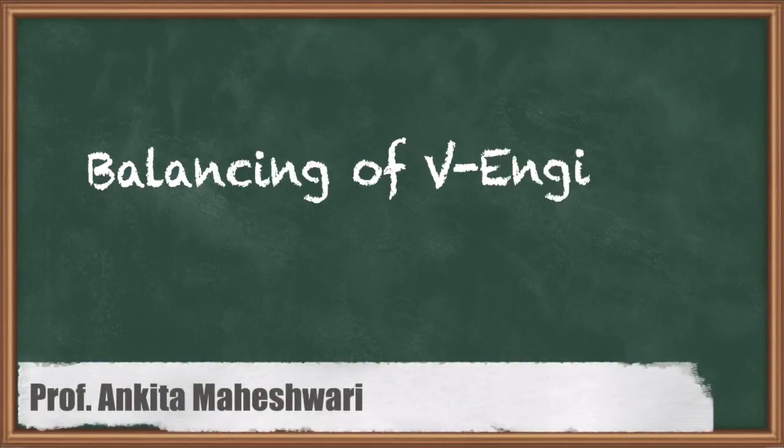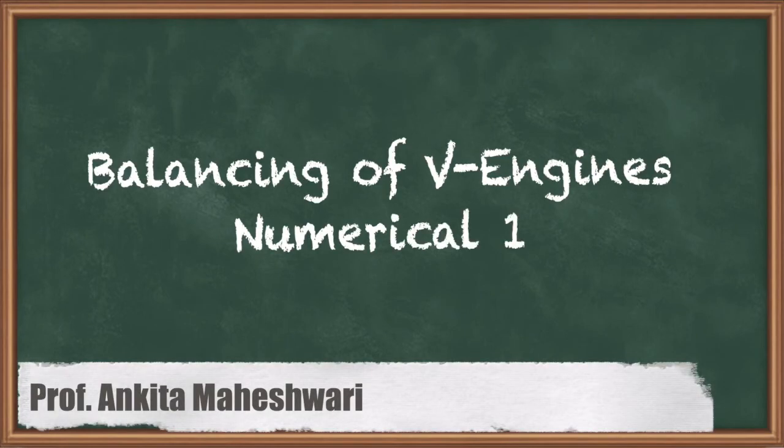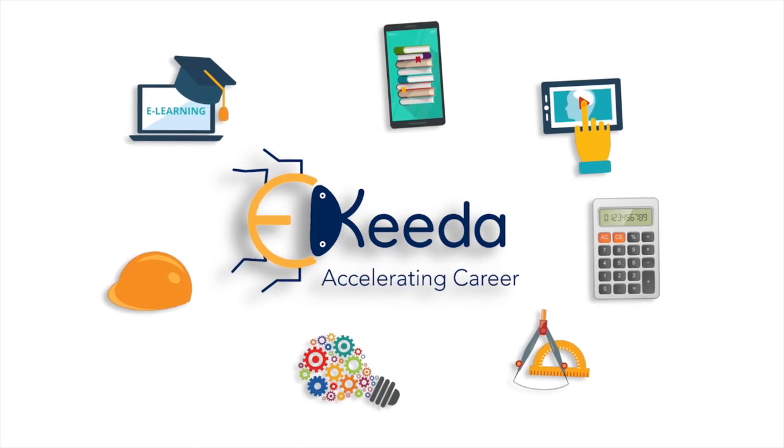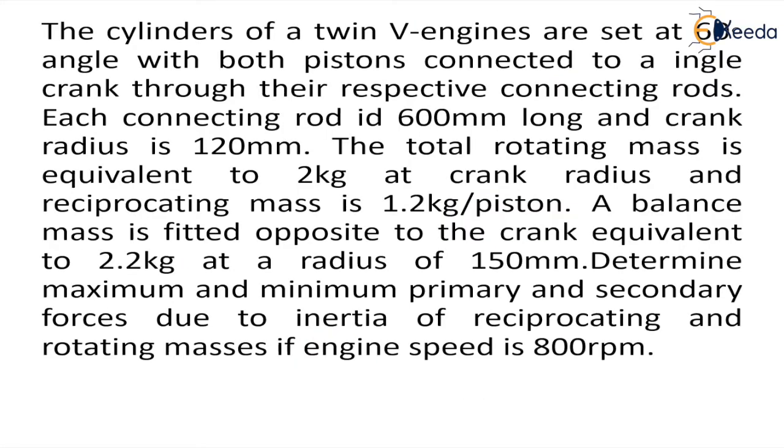Hello everyone, in this video we'll discuss a numerical on balancing of V engines. So in V engines we already know that two connecting rods run on a common crankshaft. In the question we are given that the cylinders of a V engine are set at a 60-degree angle.